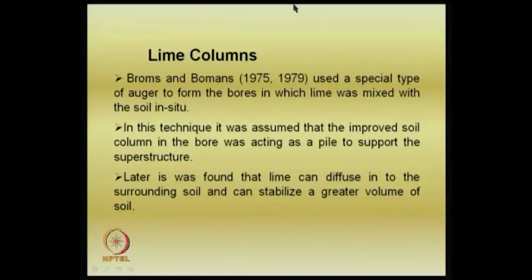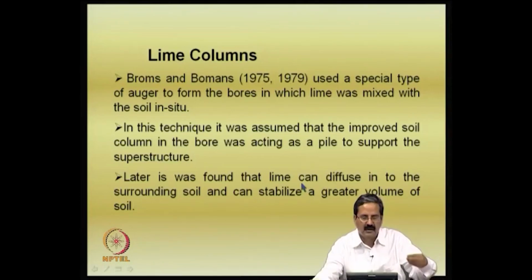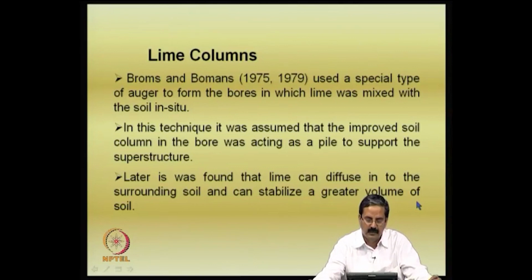People have also observed that it is not just about treating it as a pile. In fact, lime can diffuse, depending on the permeability of the nearby soil. The diffusion can take place, and the lime can in fact stabilize a larger amount of soil. It is a very important concept here. People have done a lot of work on the diffusion of lime in soils, in Madras IIT, many other places, and even at the Institute of Science.